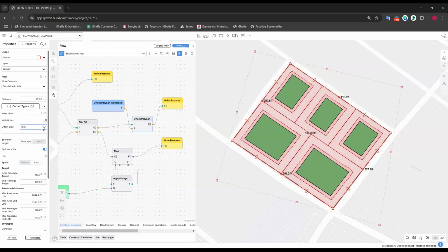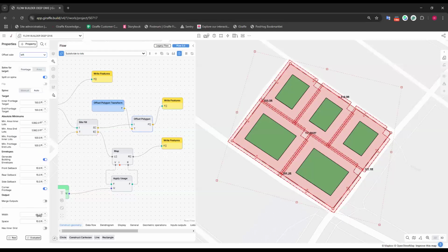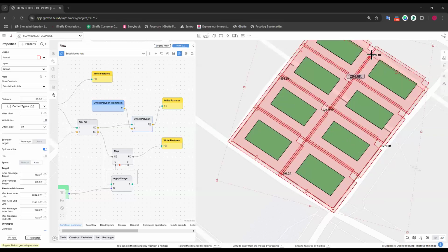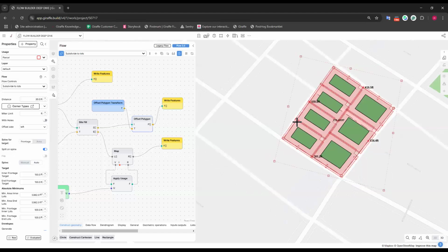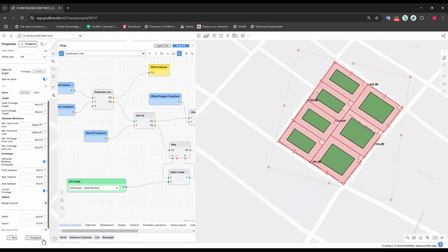And I'm just visually checking what my results are to get what I am going for here. I might need to make this parcel a little bit larger actually. Site fill works the best when it's on a pretty big site. Let me do slightly less wide buildings here. I did this off the envelope. I might need to make my setbacks a little bit larger too.